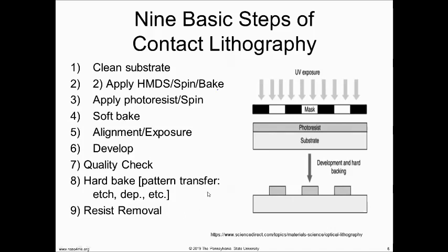A good way to chemically do that is, in some ways, add excited oxygen to that. And then my carbon and hydrogen will turn into CO, CO2, OH, and H2O. So I took this solid, apply plasma oxygen, and that plasma oxygen is going to chemically react with my organic photoresist, and it's going to make that solid into a gas and remove it. So in some ways, I chemically remove step number 9 with an oxygen plasma. Does everybody understand that? So I know through these presentations, we're discussing what is a plasma or whatever. So I want to reinforce that these plasmas are crazy cool things to know and very, very useful.